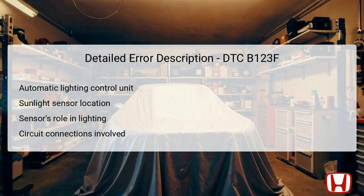It is responsible for managing the headlights based on external light conditions, enabling automatic headlights to function properly. The sunlight sensor is typically located near the top of the dashboard, where it can effectively measure sunlight levels. This sensor detects changes in ambient light, signaling the control unit to adjust the headlights accordingly. Any malfunction in this system can lead to either the headlights failing to turn on in low light conditions or staying on unnecessarily, draining battery life.